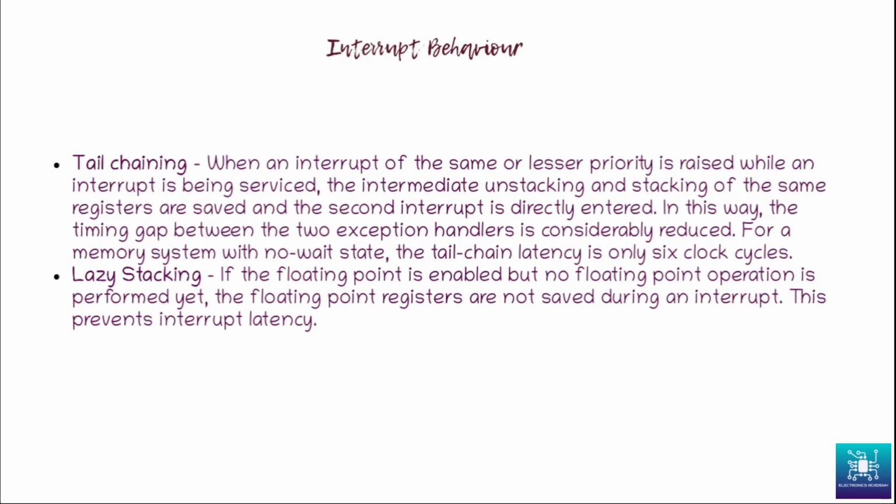So if the interrupt currently executing has a priority of say 7, the other interrupt may have come with a priority of 8 or 7. 8 means lower priority, higher number is lower priority in the case of ARM Cortex. In such a case, we know that the first interrupt is not going to be preempted. Rather, the first interrupt will complete execution and then the second interrupt will start executing.